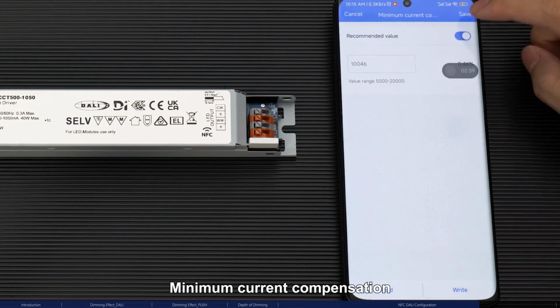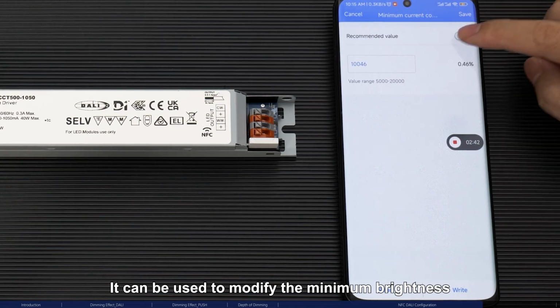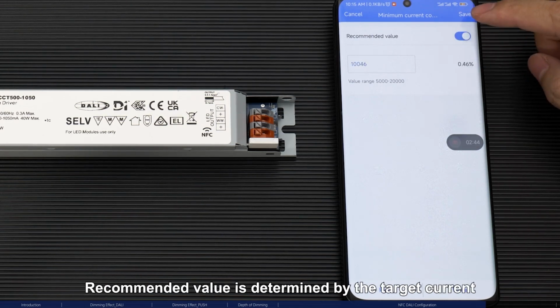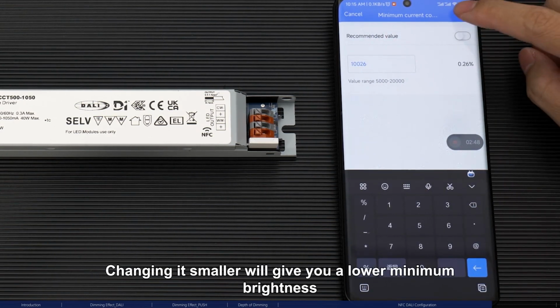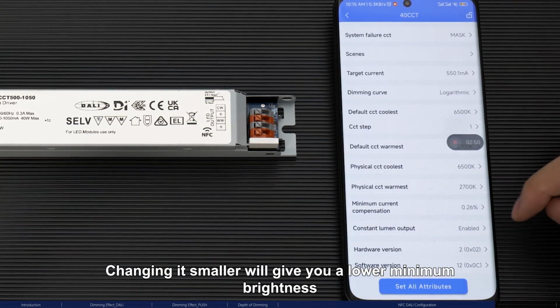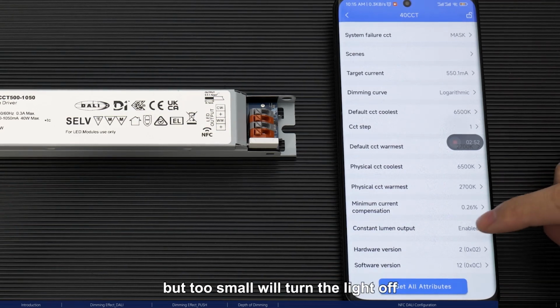Minimum current compensation, it can be used to modify the minimum brightness. Recommended value is determined by the target current. If it's not dark enough, then make it smaller. Changing it smaller will give you a lower minimum brightness, but too small will turn the light off.